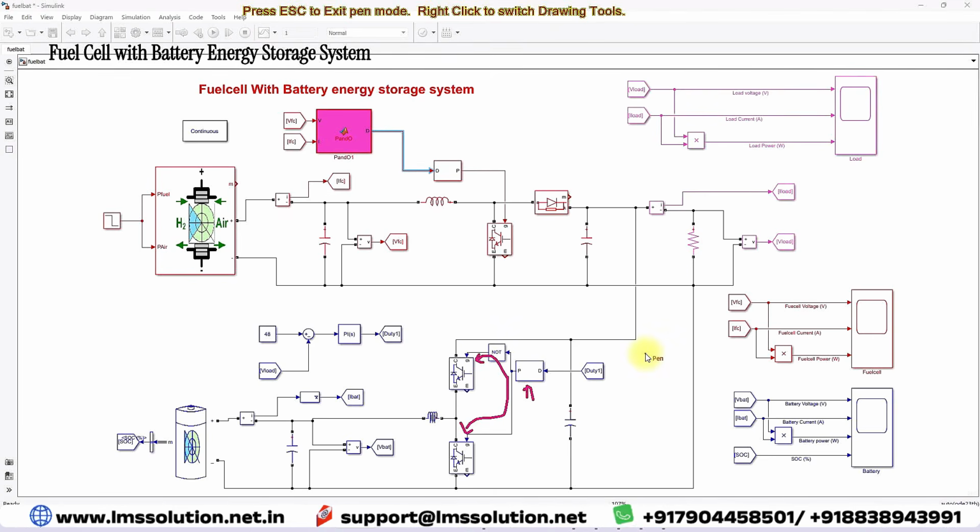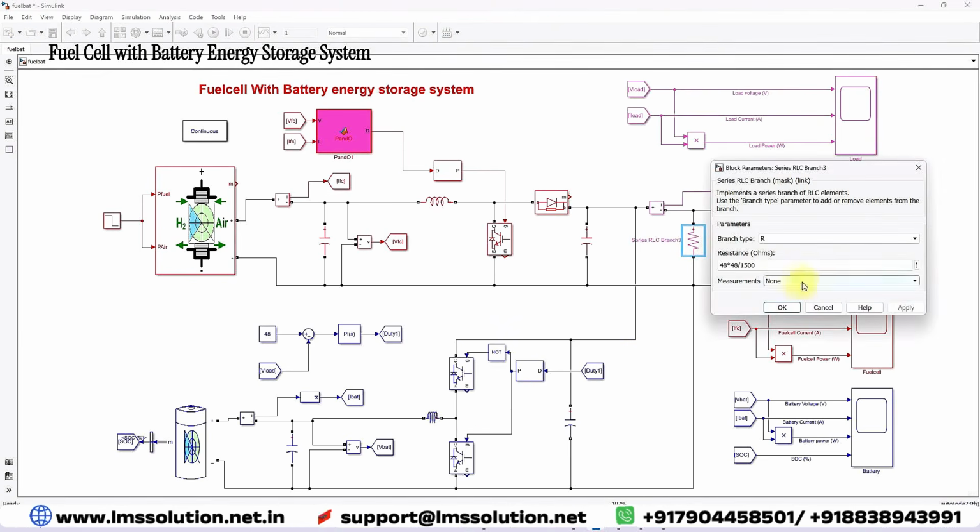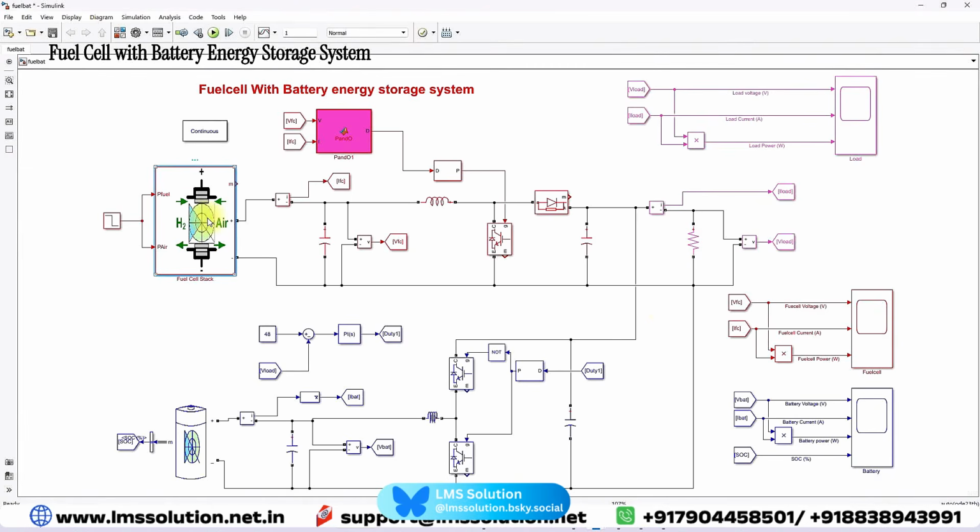And then here we consider the load as 1500 watts. That means we use the V squared by P concept. Here we are calculating the R value, P equal to V squared by R, and then R equal to V squared by P. With that concept we calculate the R value. Here the load is around 1500 watts, because if we operate this fuel cell at one pressure, that pressure of the fuel cell here will be equal to 1, it can generate a maximum power of 2000 watts.